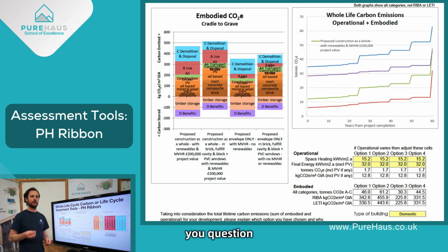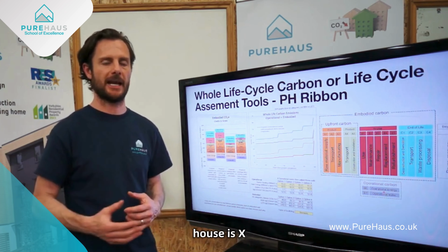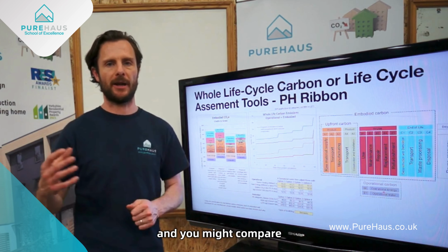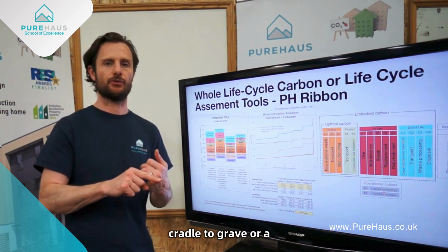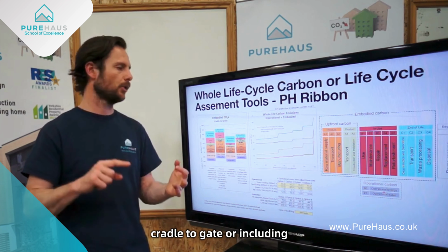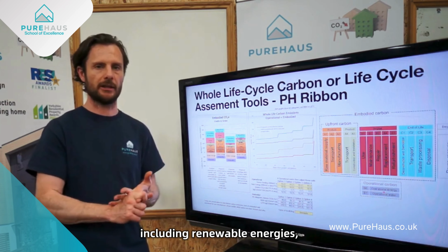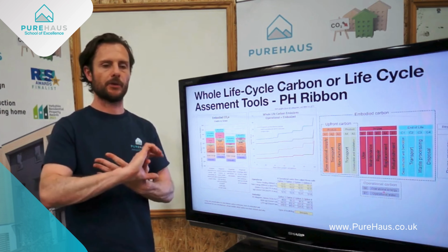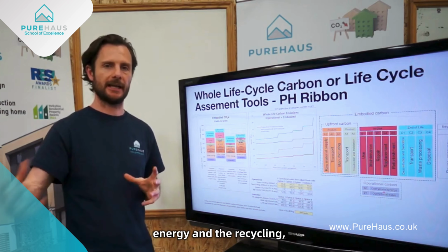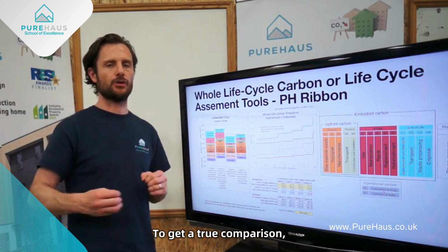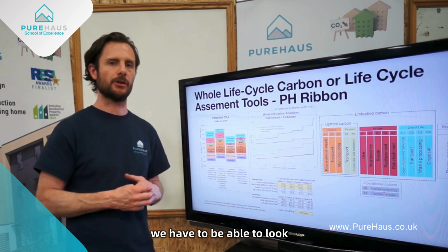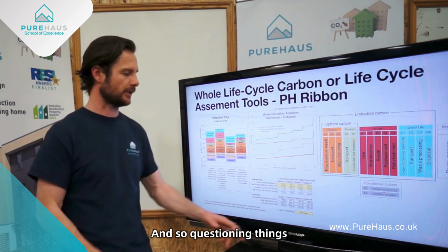What's important is that you question what it means and where the information has come from when somebody tells you a carbon footprint of a certain product or a certain house is X, and you might compare it with something else. But if that something else has been calculated using a cradle to grave or a cradle to gate, or including renewable energies or not including renewable energies, considering the occupancy energy and the recycling, how many years have they considered the building to live for? To get a true comparison, we have to be able to look at comparable data, and so questioning things is important.